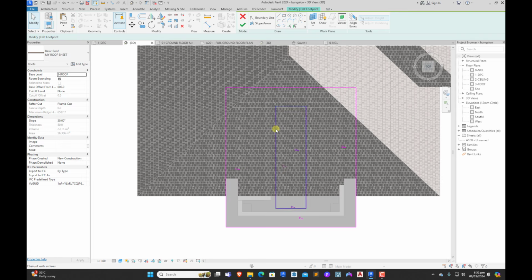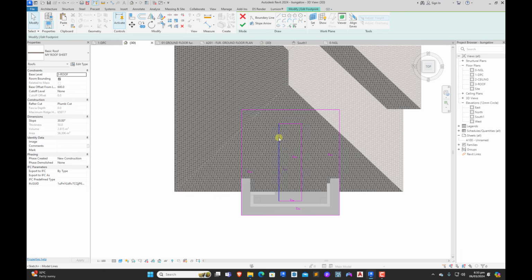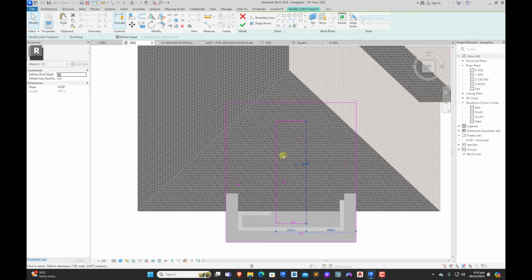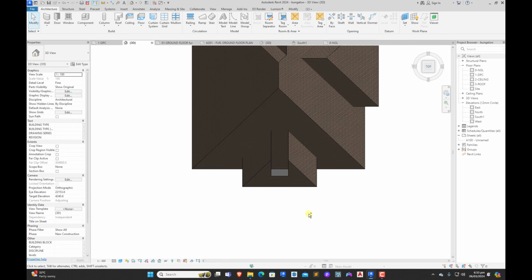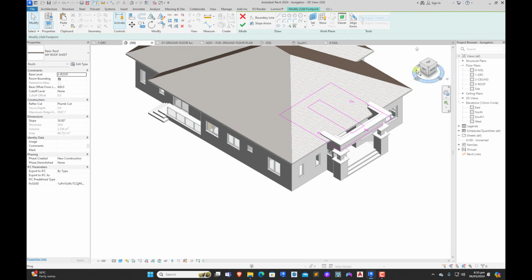Okay. Now select all this. How do we select this? We put our cursor on the line here. We click on our tab button to select, and we click. That's for us to select all linked lines or linked walls together. So with this, we uncheck the slope, select all this, and we uncheck the slope. Okay, it's only this and this that have slope. So we uncheck the slope for this, and we click on OK. Now you can see the roof. We have cut the roof.